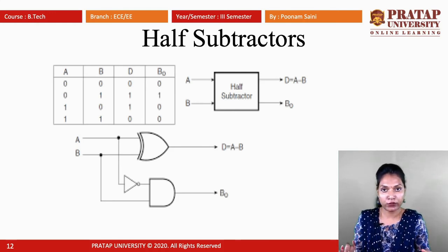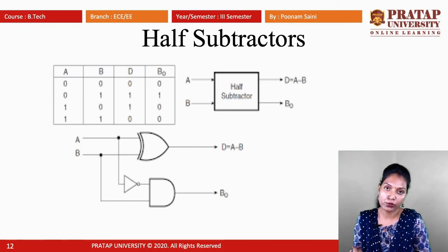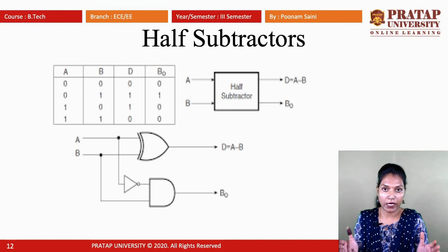In a full or half adder we have two outputs, carry and sum. In a full and half subtractor we have two outputs, borrow and difference. So today we conclude with the combinational circuits of adder and subtractor. As we already discussed, in a combinational circuit there is no memory element, while in a sequential circuit there is a memory element. That means in a combinational circuit there is no feedback part, but in a sequential circuit there is a feedback part. This is the only difference we need to keep in mind, between a combinational circuit and a sequential circuit.